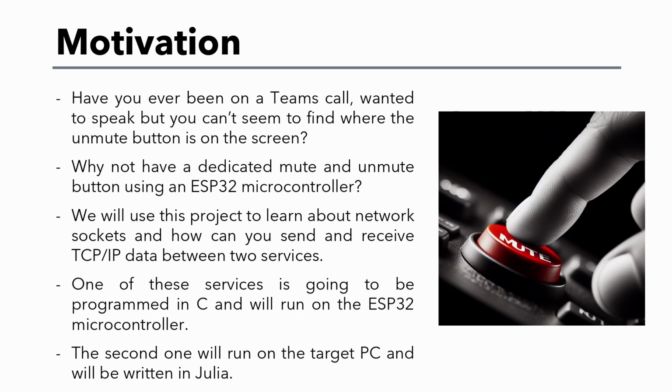You can easily find these boards cheaply on any major retailer online, and they will serve you well to create any Wi-Fi based projects that you might want to do. In this particular project, we will use the TCP/IP network sockets to send this button interaction between the microcontroller and our PC. To do that, we will program the microcontroller using C with the Arduino IDE, and then on the PC side, we will write a Julia script.